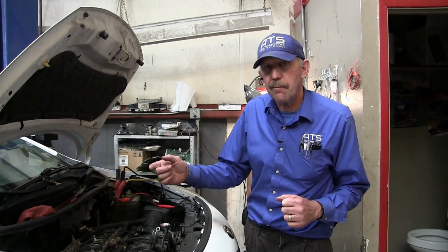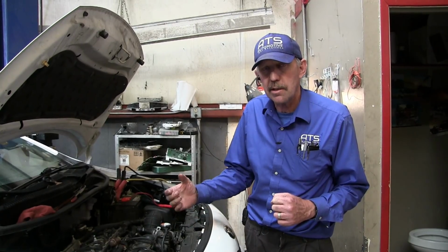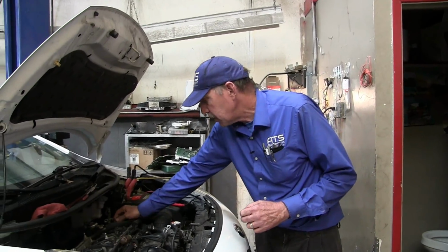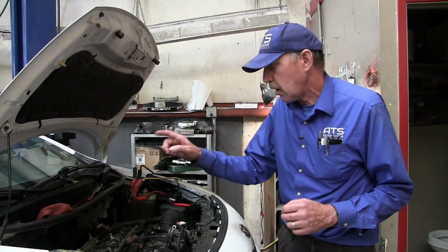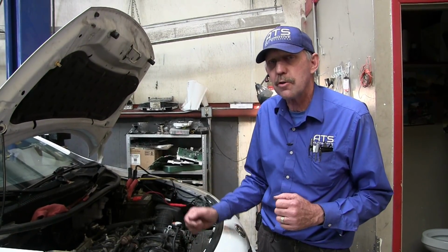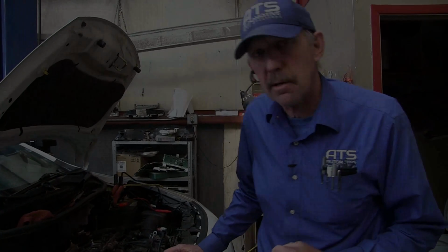So I'm going to feed the fuel out of the pump into a measuring device so we can see how much fuel is flowing out of the pump. And then I've got this line up here loose, and we're going to plug that onto the pump, and we're going to see how much comes out up here so we can try to figure out where this restriction is. So let's go ahead and take a look at what I've got set up here.